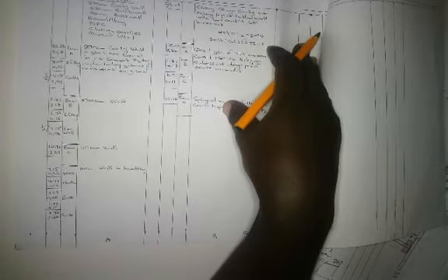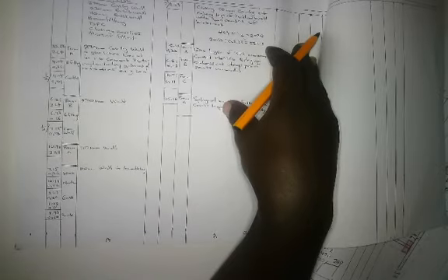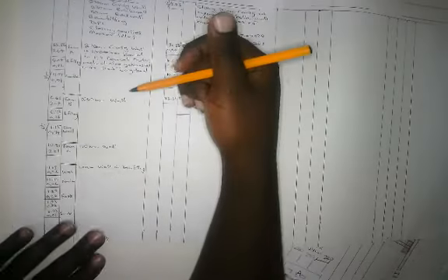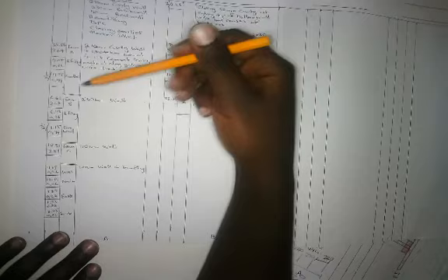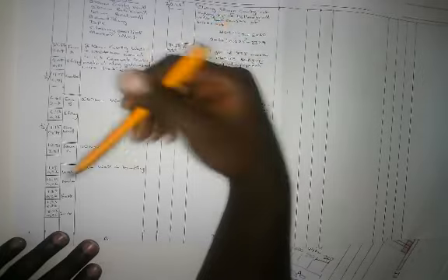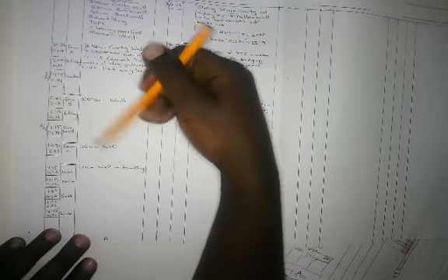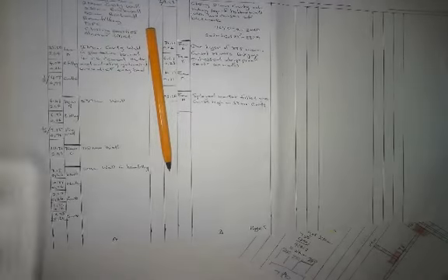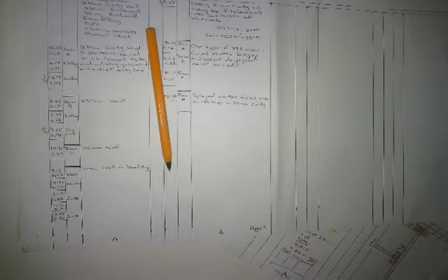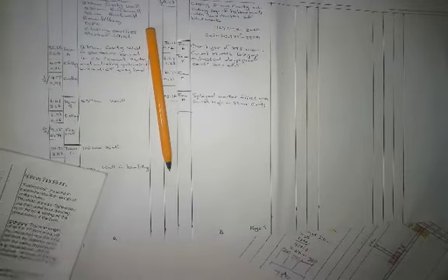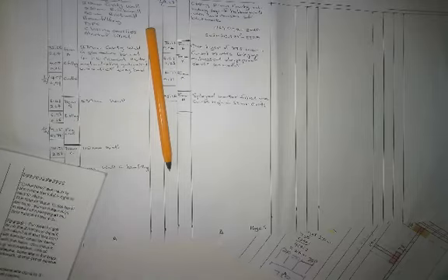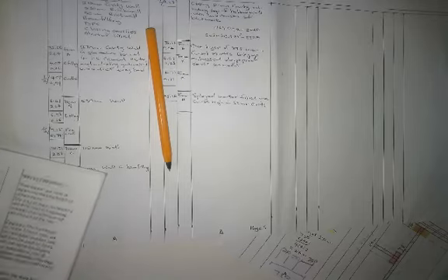And then you've got your superstructure brickwork, which should be primarily very easy because you've got your lengths and your heights. I don't foresee that you will have a problem with this one, but you still use your center line. So center line times your height. You're going to take from A, it's going to be 35.56 times 2.64. And then you will also go to your 230 wall, 6.61 times 2.64, then to your 110 wall also.